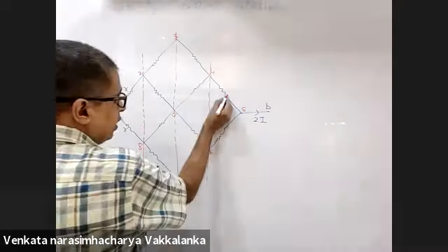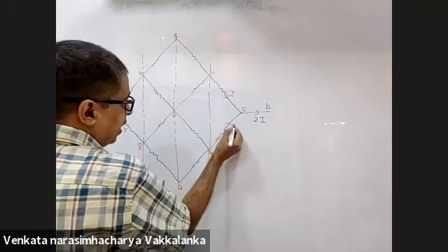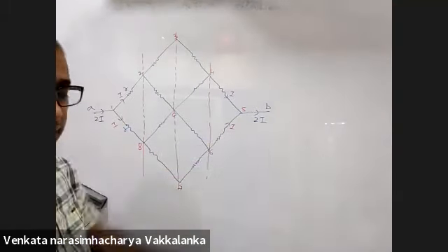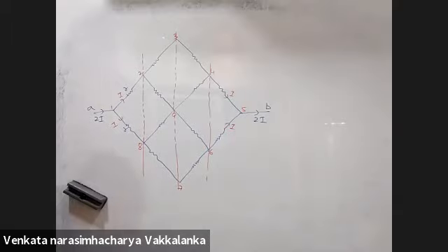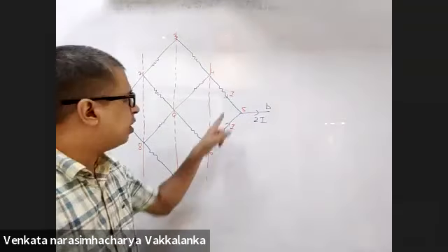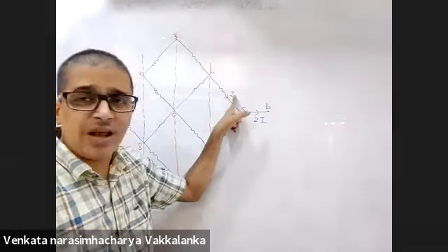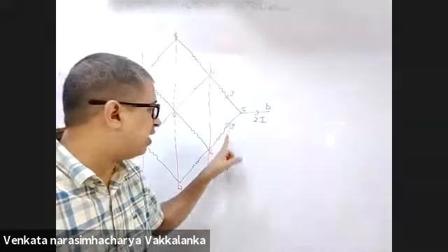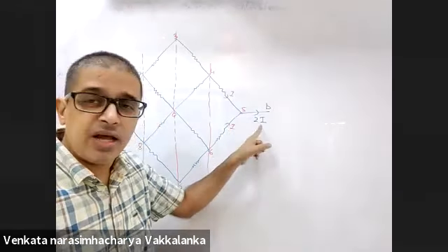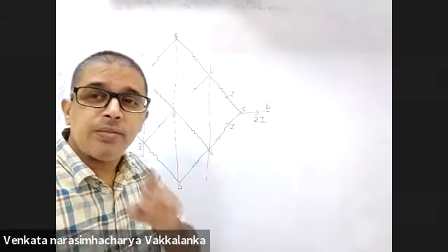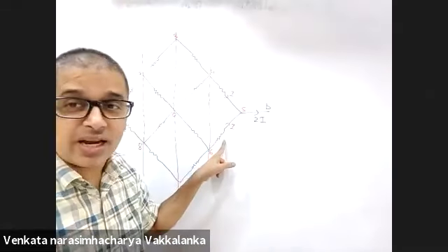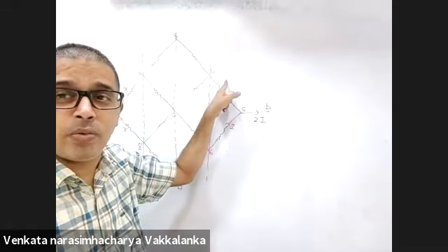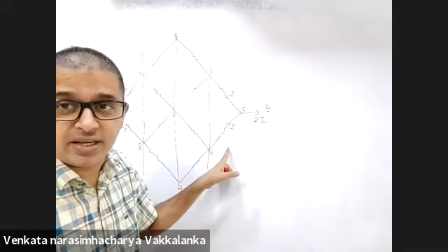Listen carefully a little. I should get back I and I here so that I get 2I here. Yes, sir. Some students may feel, why should you get back I and I here? I will have 1.5 I here and 0.5 I here. I will get 2I. The problem is resistances are identical. You cannot have 1.5 I there and 0.5 I here.